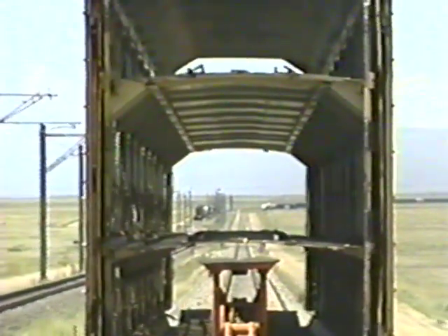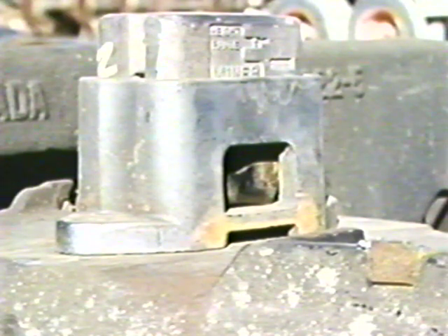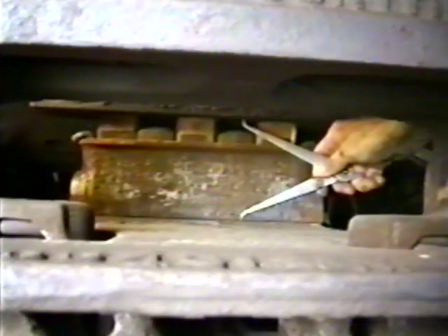In general, hunting becomes more severe with increased speed. Constant contact side bearings help to control hunting in some rail car designs. Improperly set up or worn constant contact side bearings will allow the rail car to hunt at lower speeds. The snubbing wedges in trucks also help to control hunting. As these wear or their springs fatigue, hunting will become more severe. Finally, worn wheels with a high conicity profile are much less stable than properly profiled wheel sets.